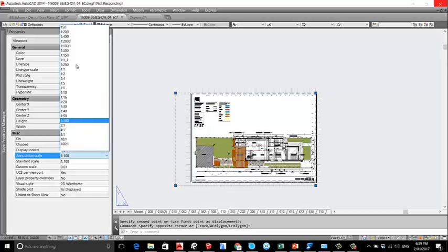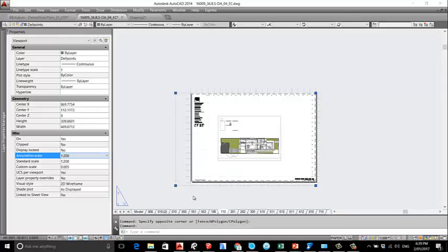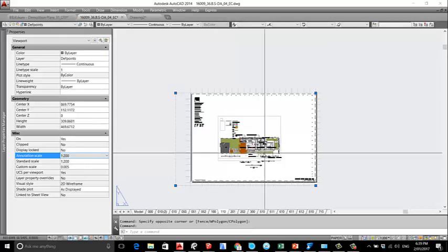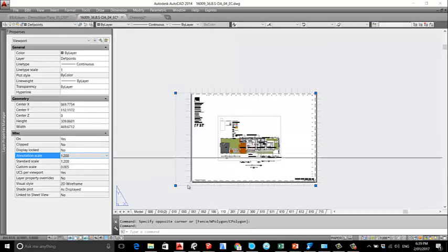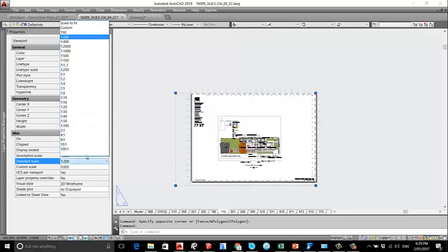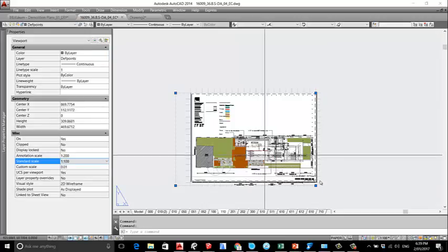If AutoCAD doesn't crash, which is crashing now. Okay. Well, one is that it automatically set the standard scale to 200. For some reason, you cannot change that without changing the normal scale, but then you can change the standard scale to 100 and get that effect. You can see 100 down here. Bam. So now here we go.